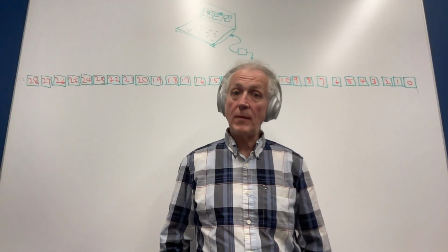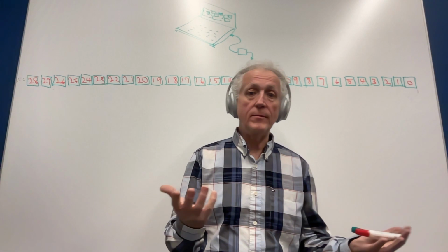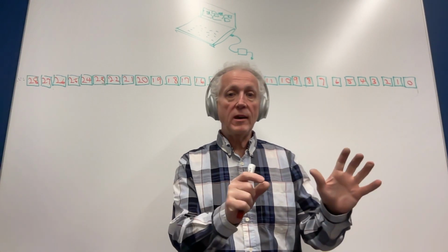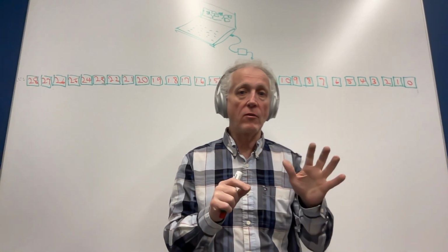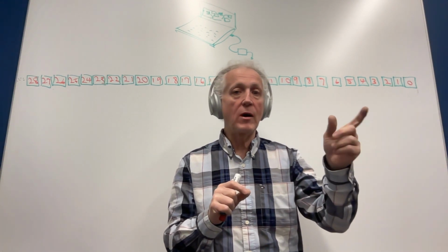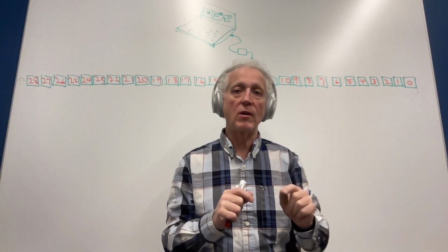Let's talk about readbacks first. And what is a readback? A readback is where we can read the data from anywhere in your program, which is a really powerful tool. You can choose a place in your program and say, okay, tell me what the data is right now.